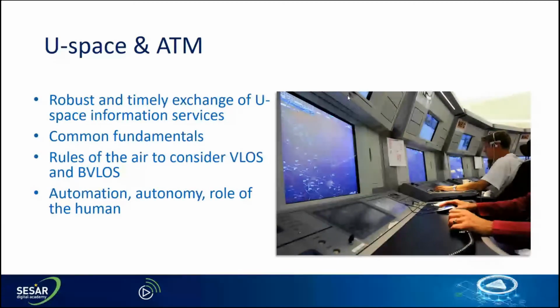We need common fundamentals. As I said, information exchange will be critical to enable a safe convergence of U-space and ATM. The possibility of a fully integrated airspace without segregation between U-space and ATM users is the ultimate goal. A fully integrated ATM U-space ecosystem without segregation between U-space and ATM operations also requires the setting up of common fundamentals. Some of these fundamental enablers refer to the definition of a common altitude reference system, separation minima, safe operating distances from buildings, and fundamental aviation tenets such as airspace classification.